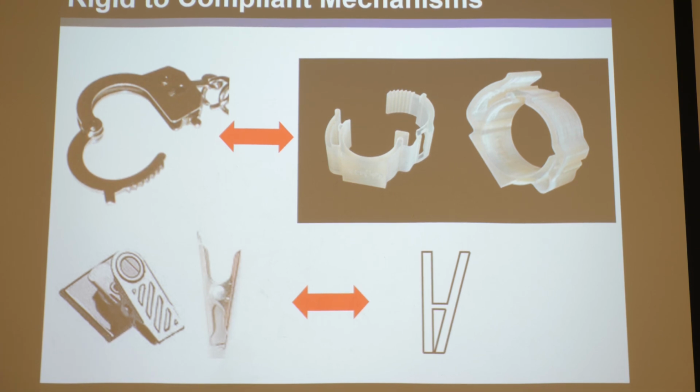You can look around in your engineering life at just products and see, oh my goodness, I could make that way cheaper, way better if I make a compliant version, go make it and put them out of business. These are name tag clips with springs, and also particularly look for things with springs inside. A lot of times people don't know about compliant mechanisms, so they just design a rigid mechanism and put like a coiled spring inside, which I don't think should be classified as a compliant mechanism, even though technically it's got a compliant part. It's a rigid mechanism with a coiled spring is what it is. But if you ever see a mechanism like that, you can almost certainly replace it with a compliant mechanism version where the whole thing is a single piece.